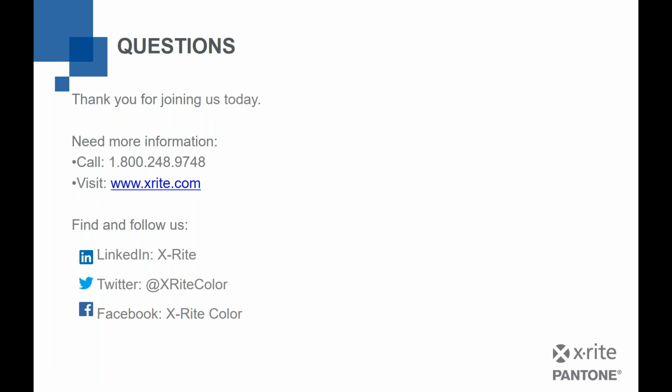One last comment, just because I saw a question pop up. I didn't even read the whole question, but I just saw LED. Yes, the world is moving to LED lights. The CIE has defined LED illuminance or spectral power distribution, and we do have an LED light kit to allow you to put certifiable, CIE-meeting LED lights into a booth. The scary part is that the LED lights you go buy somewhere to put in a room wildly vary all over the place, so that's a caution. There are about 20 LED illuminants defined by CIE, but we do have the ability to include LED.